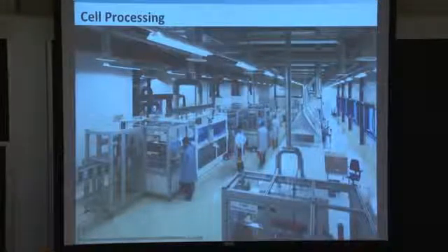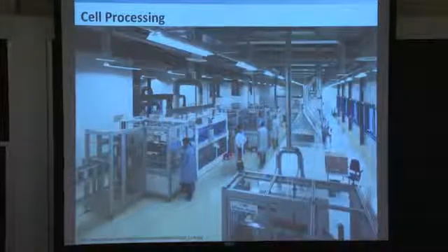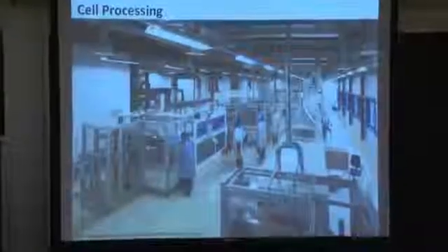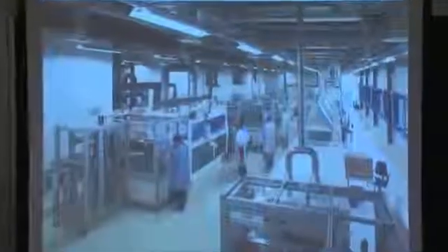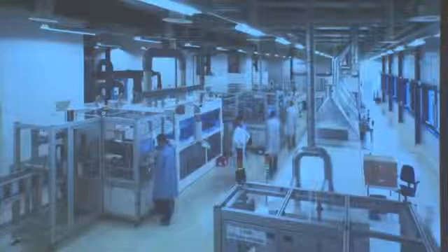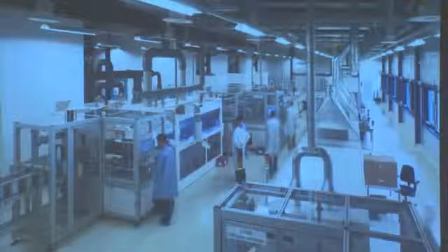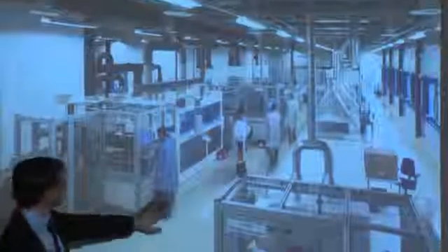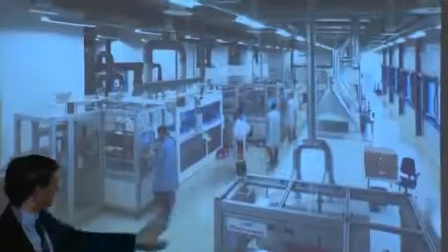So in wafer fab, which means wafer fabrication, in the section of the company dedicated to producing wafers and ingots, it was a little bit more dirty. You had forklifts moving these big crucibles around with chunks of silicon in it, operators coming by with garden hoses and washing down furnaces after they're finished. Here in the cell fab line, it looks almost more like a clean room. Almost, I say, because these folks aren't in full bunny suits. They're usually just with jackets, with booties.